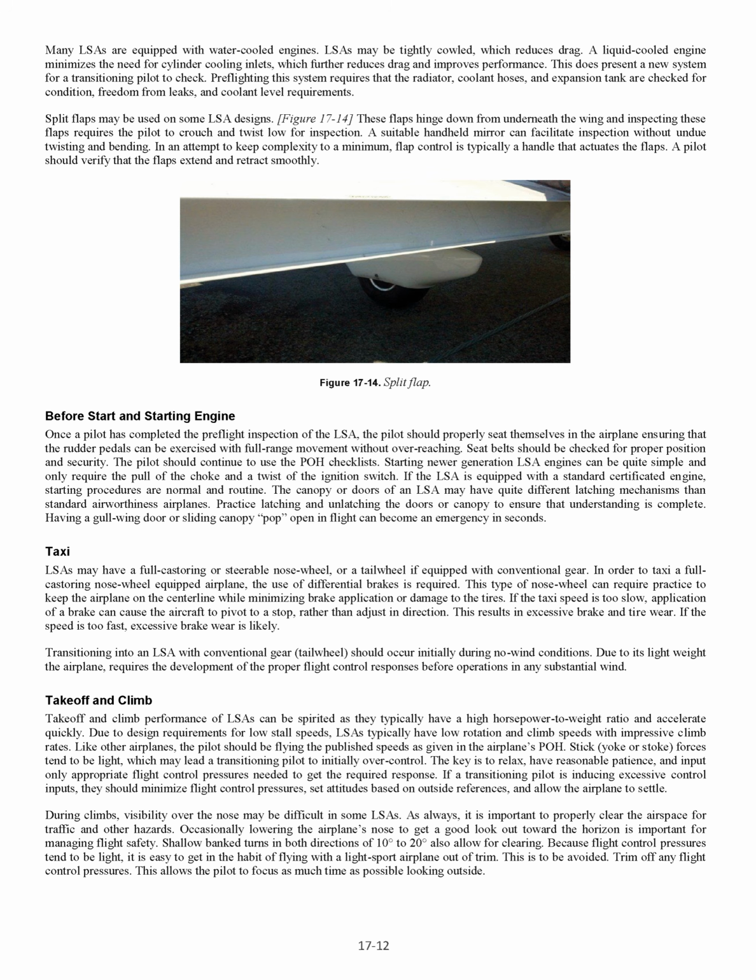Before starting the engine, once a pilot has completed the pre-flight inspection of the LSA, the pilot should properly seat themselves in the airplane, ensuring that the rudder pedals can be exercised with full range movement without overreaching. Seat belts should be checked for proper position and security. The pilot should continue to use the POH checklists. Starting newer generation LSA engines can be quite simple and only require the pull of the choke and a twist of the ignition switch. If the LSA is equipped with a standard certificated engine, starting procedures are normal and routine.